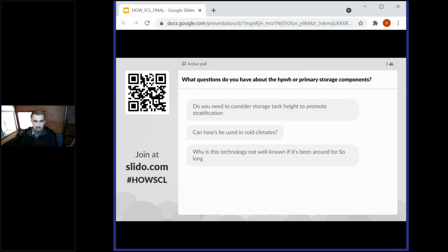So taller, narrower tanks are better for stratification, and you need to think about the sensor placement, which you can coordinate with your manufacturer, because the sensor that's telling the heat pump when to turn on and off is going to be looking for that change between hot and cold. So the height in the tank is going to be really crucial for the placement of that sensor.